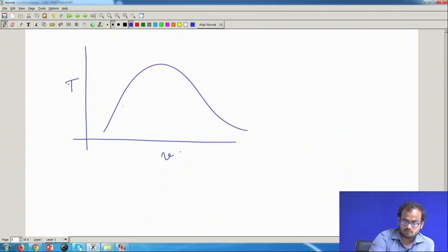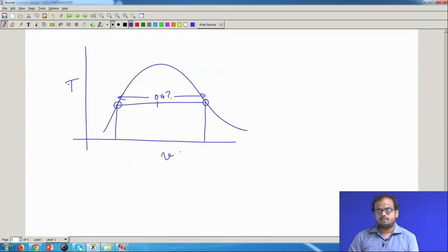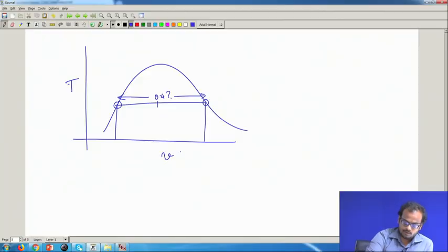Essentially, you would check if 0.4 lies between this particular point and this particular point. Is 0.4 over here, or does it lie somewhere between the vapor and the liquid? If yes, then the fluid is in a two phase region. Okay. If no, then we have to check if the volume is larger than this or smaller than this.